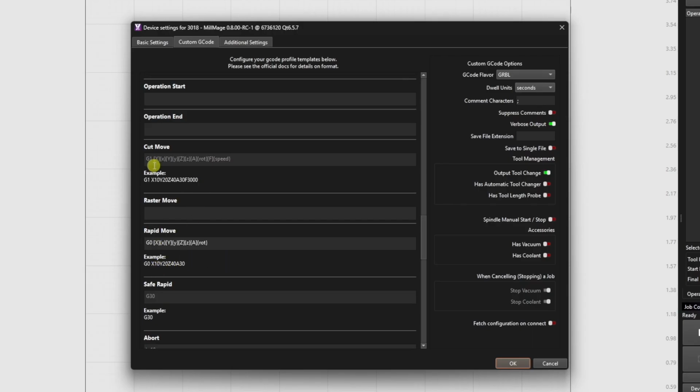And as you'll notice, in this case, there is X. You'll see this weird notation where it's X, X, Y, Y. The thing in the square brackets is the actual axis that you're emitting, so the X value. The fact that it's in square brackets basically tells it if this variable value hasn't changed, don't emit it at all. So if the job is told to move Y in 10 millimeters and nothing else has changed, it will only emit G1 Y10. That's it. Or whatever the absolute position is or something like that.